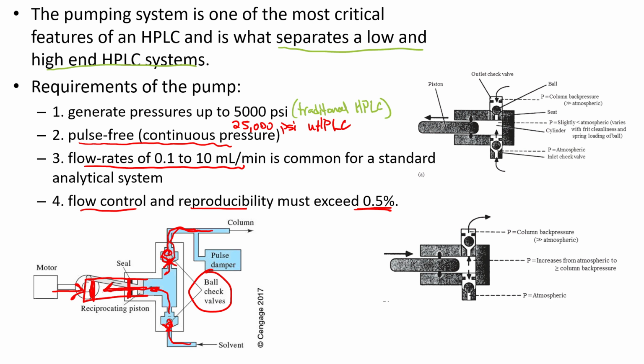All right, so you have to have good seals in here that control that, and these things have to be cleaned. The seals wear out, these little ball valves wear out, so there's a lot of consumables in this, and it depends on how dirty your solvents are, what salts are in there that kind of grind up the plastic Teflon pieces. You can take care of these valves and they last for years, or you can be abusive to them and they last a matter of months.